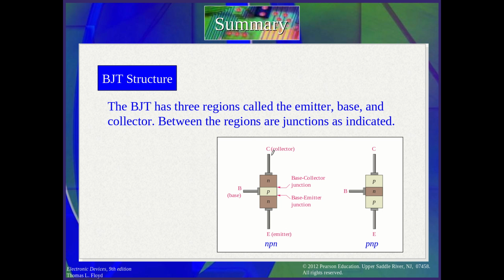There are other quantities that you should understand and know. We use VCE with capital letters in the subscript to indicate that this is a DC quantity. We use lowercase and italic to indicate that this is an AC quantity, because maybe it is a time-varying signal, not a DC quantity. Now we have some internal resistance in the transistor.